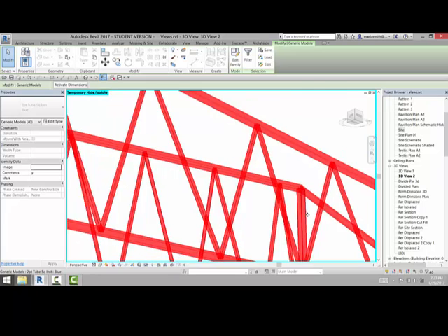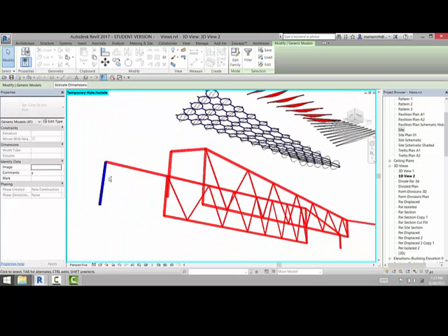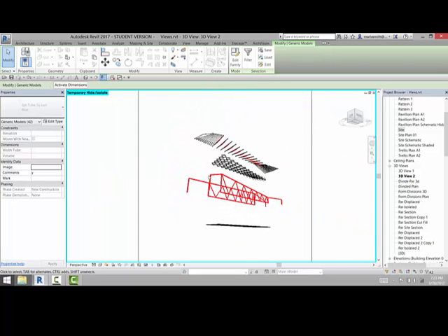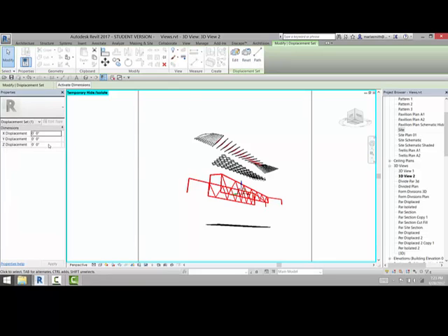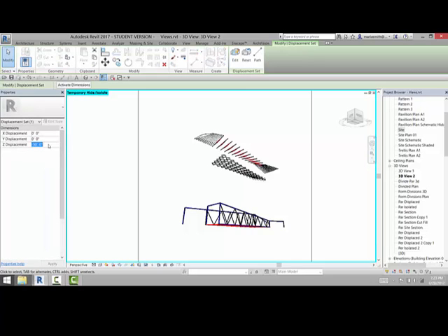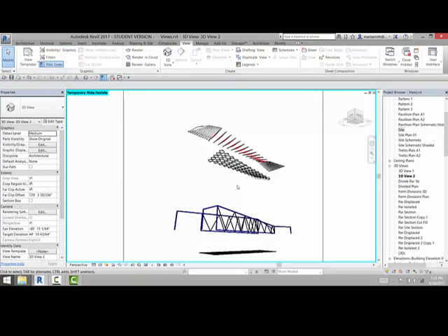Let's go ahead and get that, and that, and immediately save a selection set. So save that, save it as 0 frame. Okay, so now I want to push that guy down, and I think I'm going to make a displacement set. I'm going to take that guy down to like maybe 50 feet, which is where I had the other one. Oh, negative 50. Right, and then I'm going to pick that selection one, and I'm just going to take that down to like negative 80 feet. Right, so now we've got those guys.